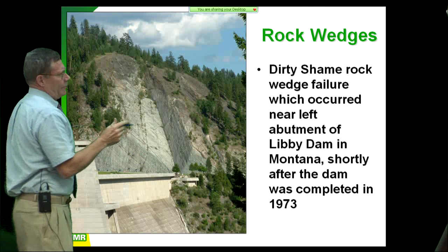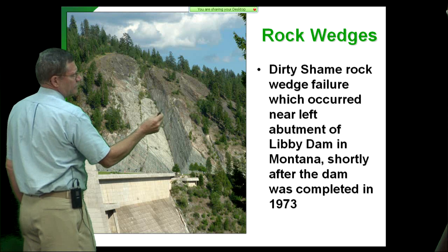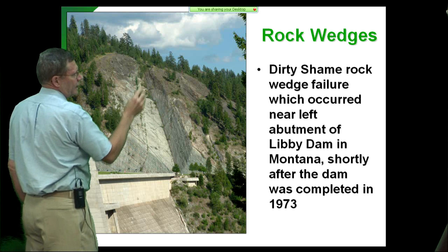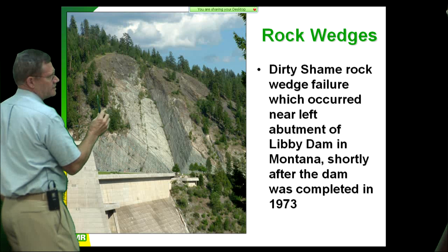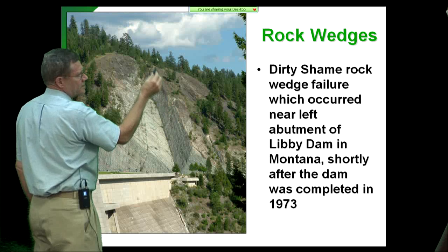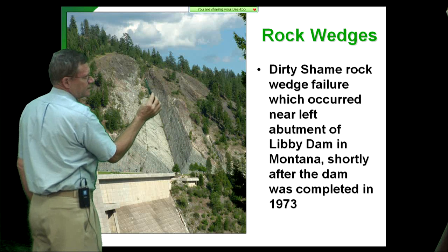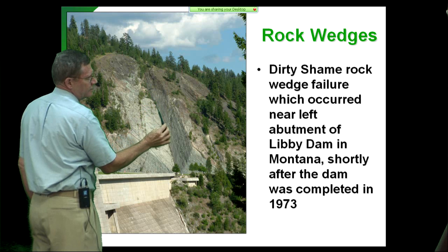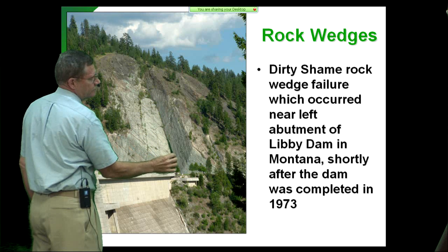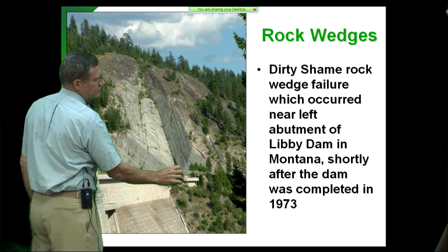This was during the Vietnam War. So they had to come in here and put in a whole series of rock tendons, big, huge bolts. And what happened here, you can see this is the bedding plane right here, and this is a joint surface that's almost orthogonal to the bedding. And this is the zone, the intersection. That's the intersection, the wedge intersection.